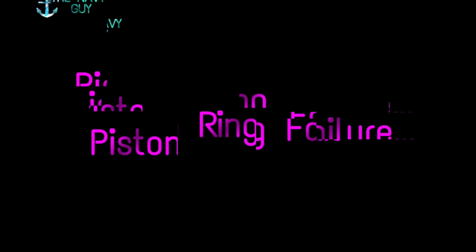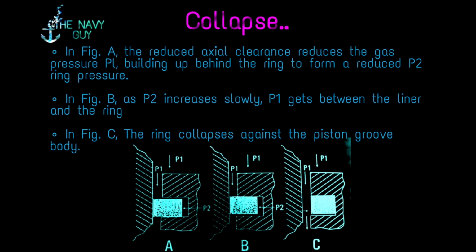Let's talk about piston ring failures. Collapse. It is the collapse, inward push of the ring against the piston body due to gas pressure buildup against the running face of the ring. It is caused by the pressure buildup against ring running face and liner wall due to reduced axial clearance, poor ring and groove sealing, rings not free to move in the groove, or poor lubrication on sealing surfaces.